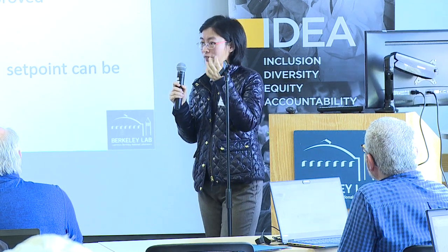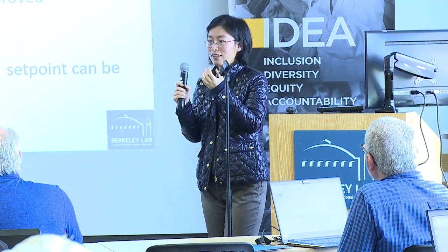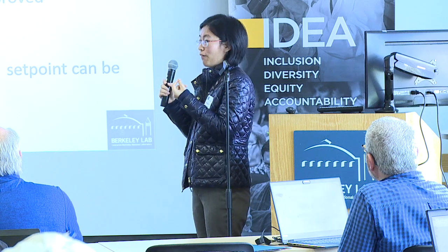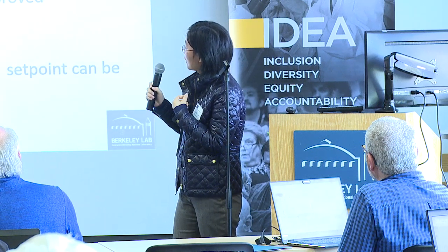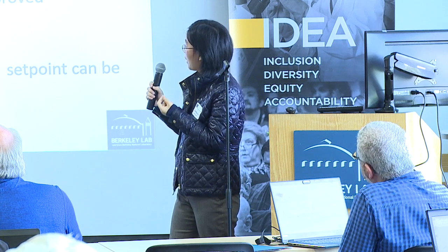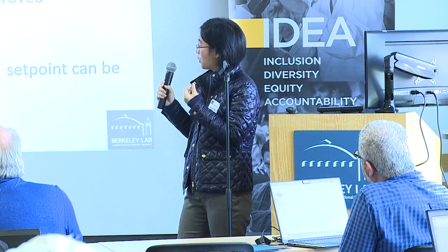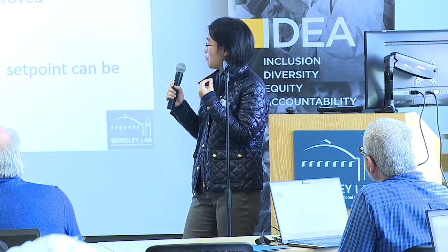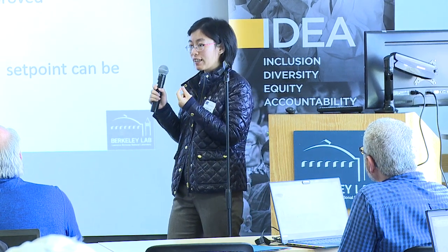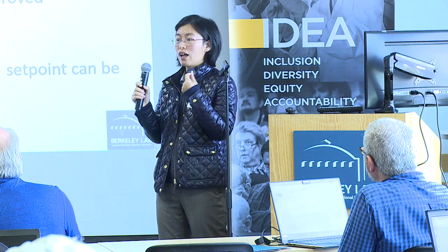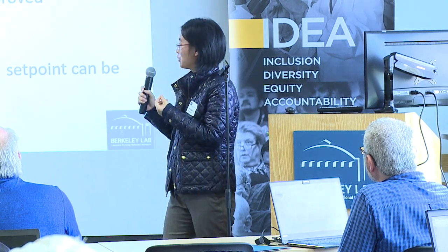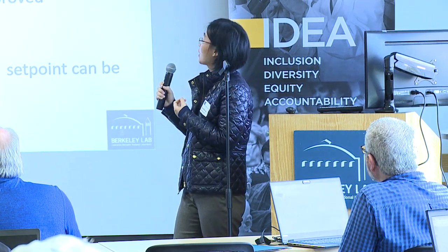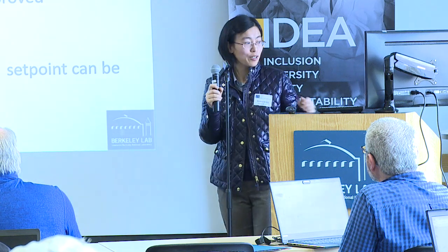Then we can find a way to add this bias into the measurements or have other approaches to overwrite the values. Another one is the damper control hunting. This one also depends. If the hunting is caused by an imperfect PID parameter setting, then we have a chance to correct it. But if it is just because of capacity and other physical damage, then that is not correctable. So it is one in between.